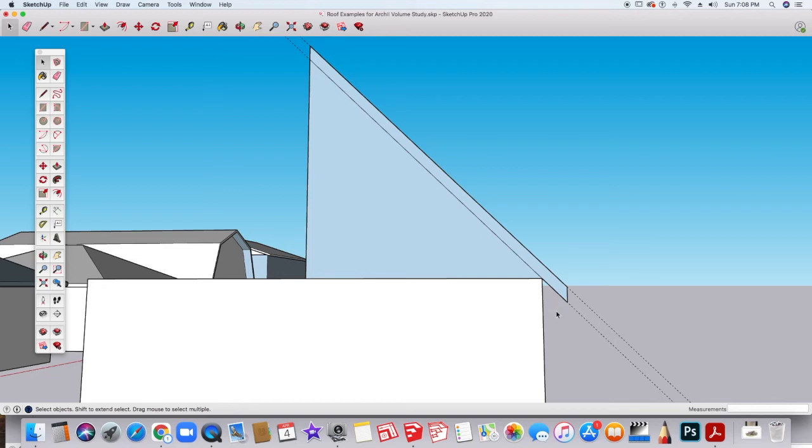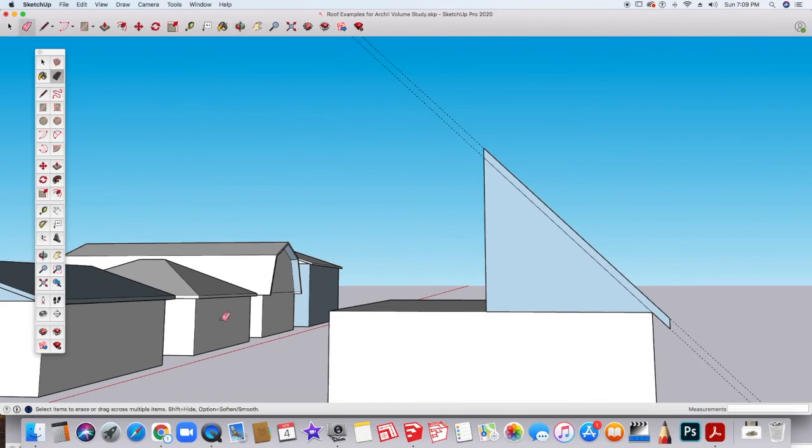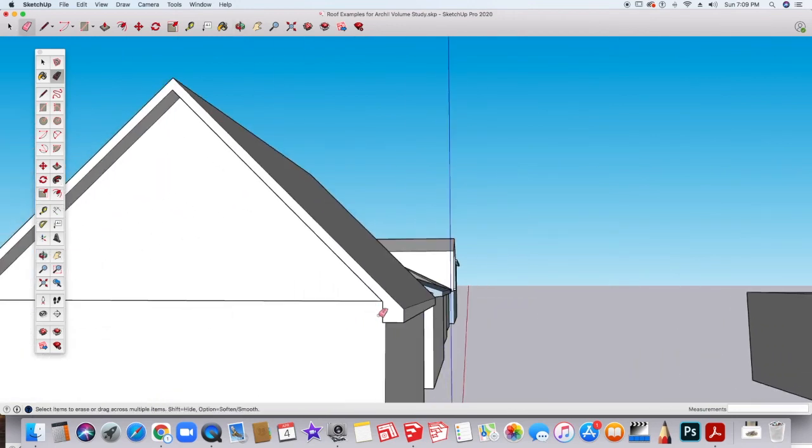It's up to you how you'd like to do it. It's sort of a stylistic choice. If you want to make a closed rafter, you would just draw a line like this going across and then up again, and you would click this one to go away and you would get that boxed rafter. If you didn't want that, you wouldn't have to do that at all, and you could just click like this. It's entirely up to you. I'm going to leave this one open since my other example over here is boxed.